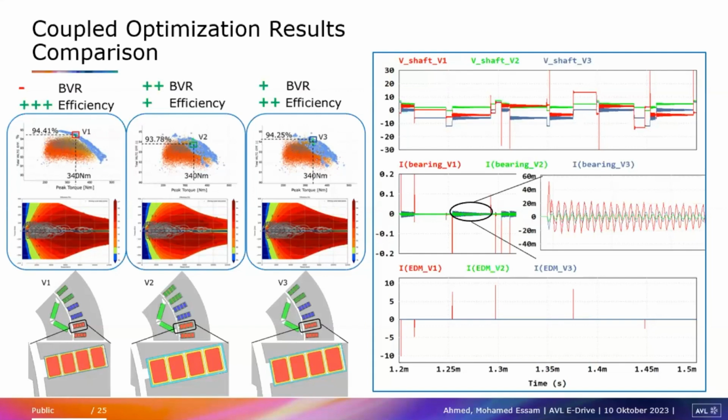But most of these tests have time dependency. For example, you stress the insulation for 1 minute at 50 hertz, or whatever. So we proposed that the electrical field solver can have a time domain or transient solution.